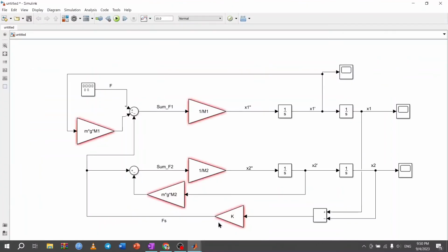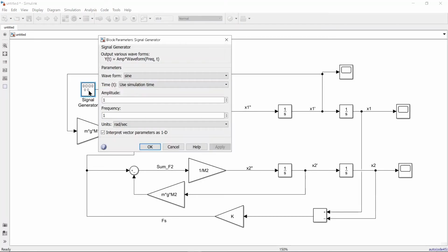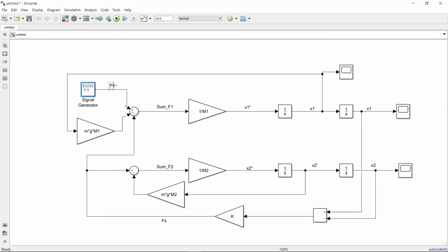So go to the Simulink, run here. We can see the red marks are gone. So the Simulink has automatically read those values I have assigned. To manipulate the function generator, I will give a square wave and the amplitude will be -1. Why -1? I will come back to that. And frequency will be 0.001 hertz. Apply. Okay. I will take another scope from this function generator. Alright, so let's run it.